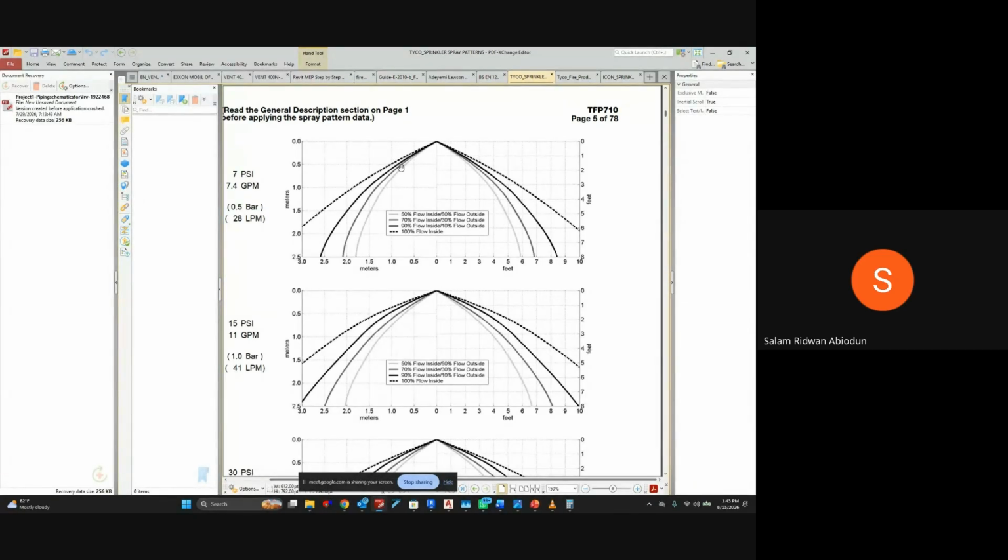But in the same office space where they are not doing anything different, it's still an open office, you just partition it. Why would you say this place is light hazard and this place is ordinary hazard? If I'm your client, I will ask you why this place is light hazard and why this one is ordinary hazard. What will you tell me? So you have to consider everything, whether it's the same function, or if they're doing the same thing.